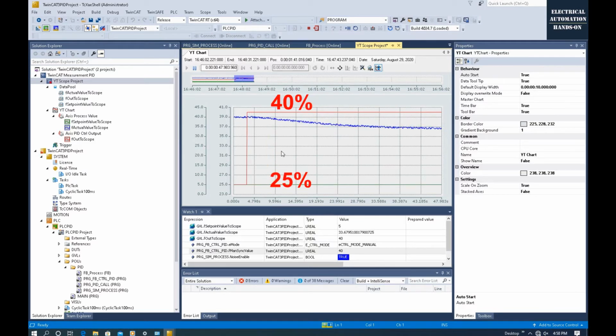With this window size, we can adjust the range of the x-axis. Because this is a cooling system, once I increase this output, the temperature drops. In the meantime, we can record: as time changes, we change from 25 to 40%, and the temperature changes from 40 centigrade to basically around 34. The system basically reaches a stable status.